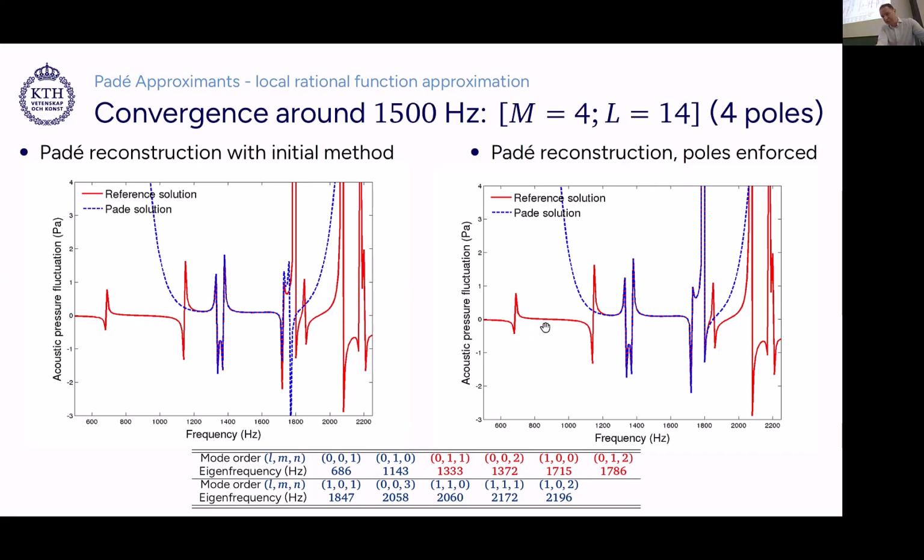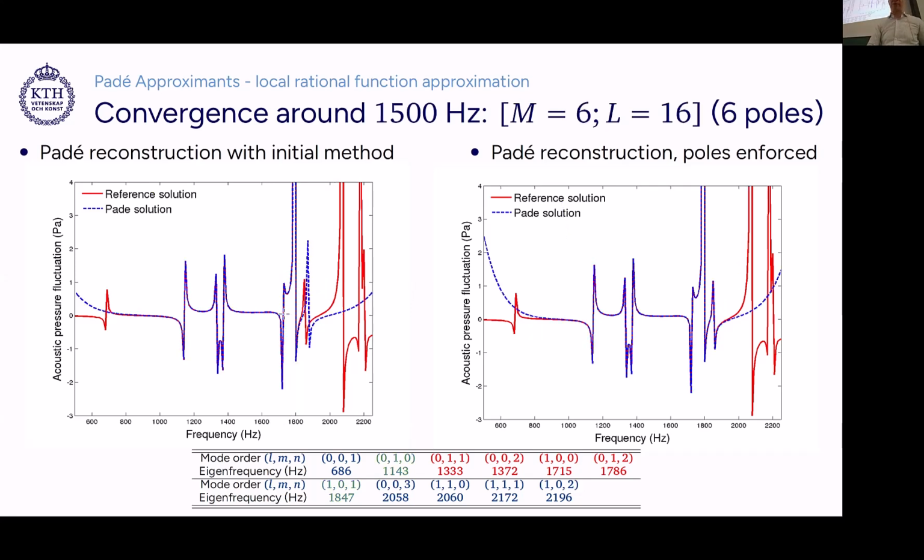What we get to see is essentially fine. We have good convergence in the middle, but you can start to see at the boundaries, which is where it's most interesting and where it should be converged, that here you fully captured what you know you should capture, 1786 Hertz, where here it's not completely the case. You don't really control that. It may be associated with the loss of accuracy when you are going to the higher orders in terms of the successive derivatives.